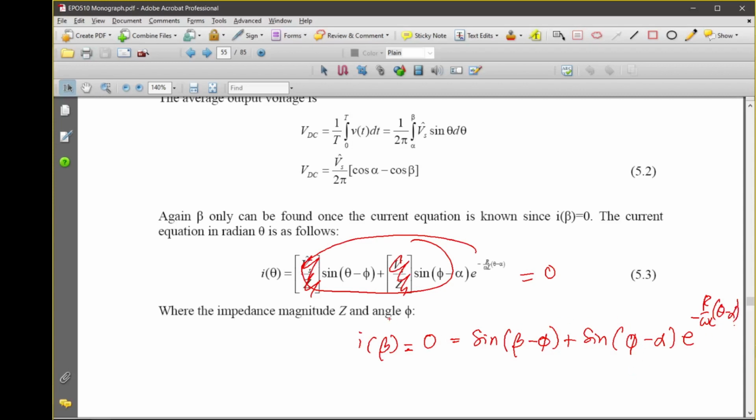Again, please make sure that when you evaluate or calculate, your mode must be in radian. Everything should be turned into radian, not degree. Remember that. When you deal with the controlled rectifier and the rectifier equations, make sure everything is converted into radian. You can find that easily by using the calculator and calculating one by one.